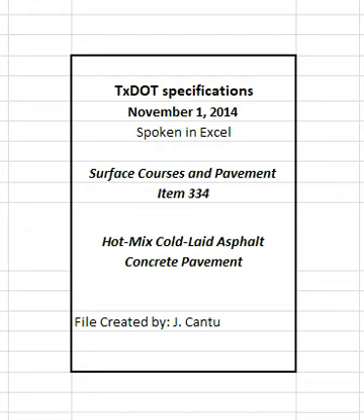Table 2. Gradation requirements for fine aggregate. See table in specifications. Sieve size and percent passing by weight or volume. Sieve size 3/8 with 100% passing. Sieve size number 8 with 70 to 100% passing. Sieve size number 200 with 0 to 15% passing.